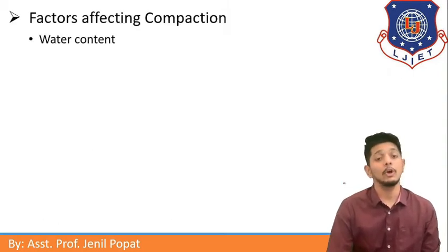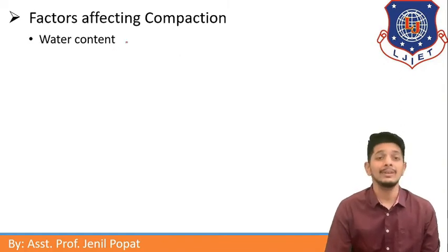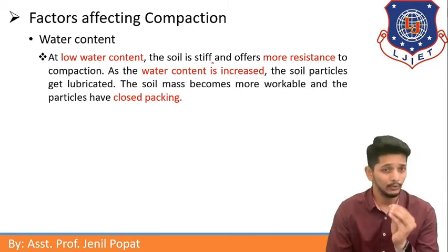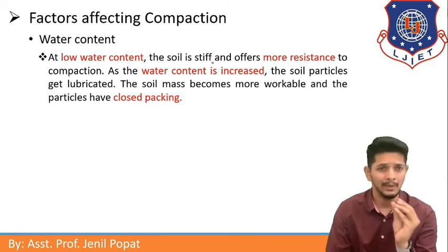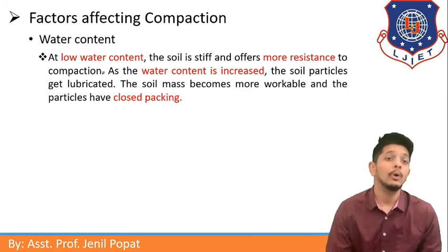Factors affecting compaction. So water content and how it will affect compaction. Let us see that. At lower water content the soil is stiff. It will not move much and offers more resistance to compaction.